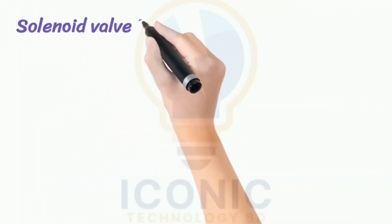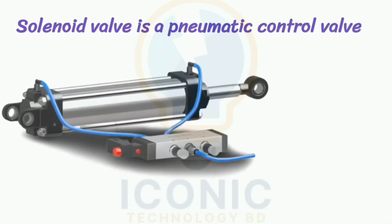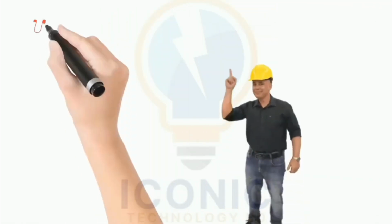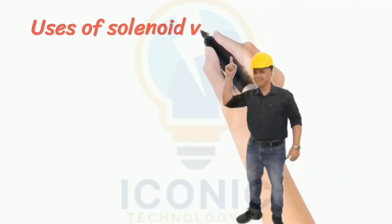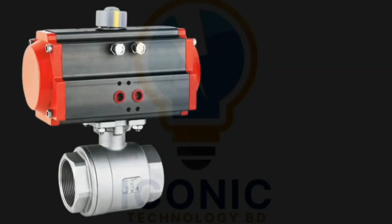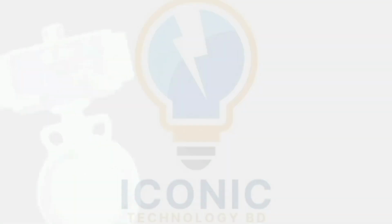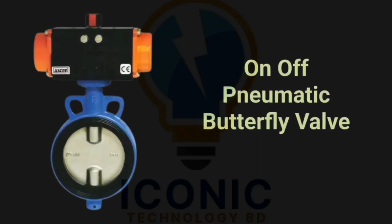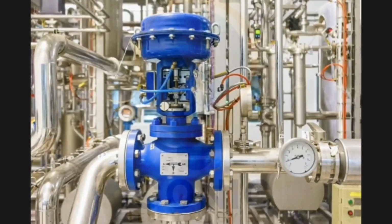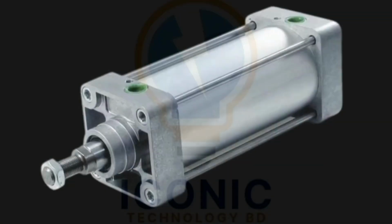Solenoid valve is a pneumatic control valve. Meaning, this valve is operated by instrument air. Let us see some applications and uses of solenoid valve in industries. This valve is used for on-off pneumatic ball valve. It is used for on-off pneumatic butterfly valve. It is used for on-off control valve. And it is also used to operate the pneumatic cylinder.